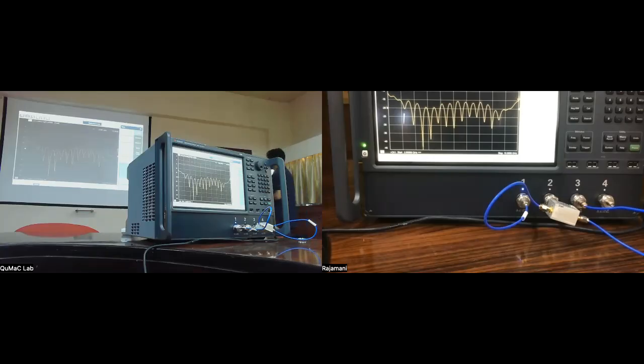Then you know that if I put 2 completely independent signals, on an average, I'm going to get half the signal on the sum port and half the signal on the difference port. And you only have access to the sum port. There are 4-port versions of this device as well, where the 4th port is actually outside and you can look at this. So this is something we'll see later on.